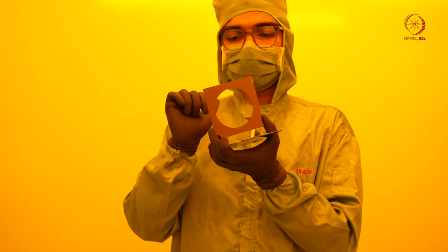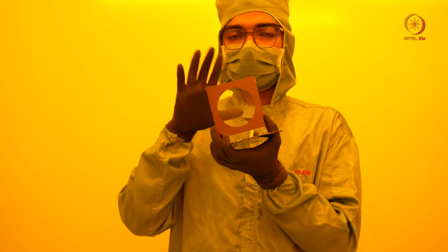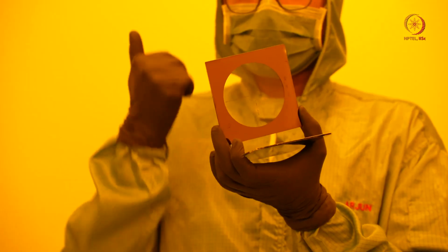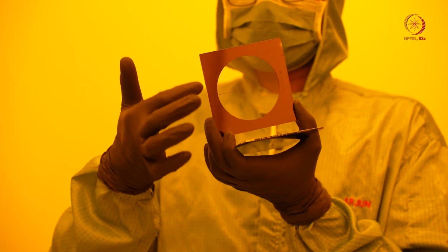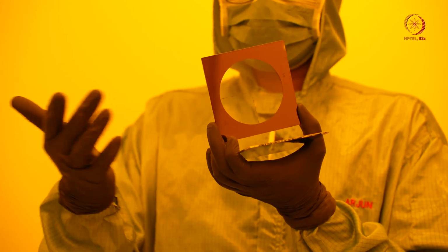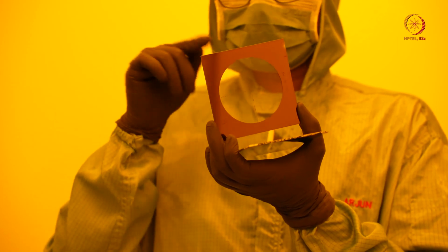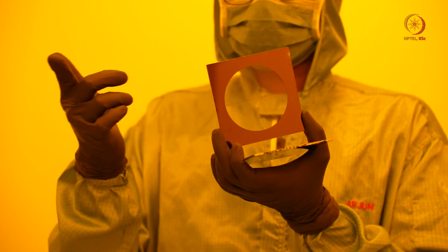Now this combination, a bright field mask and a negative photoresist, can be used for lift off. Why so? Because the pattern that we need is where the metal should come. So when we have photoresist and it is exposed, the soft areas, which are the patterns, will get removed during the development process, and when we deposit the metal in those gaps in the photoresist, the metal will get deposited. So that's a lift off process.